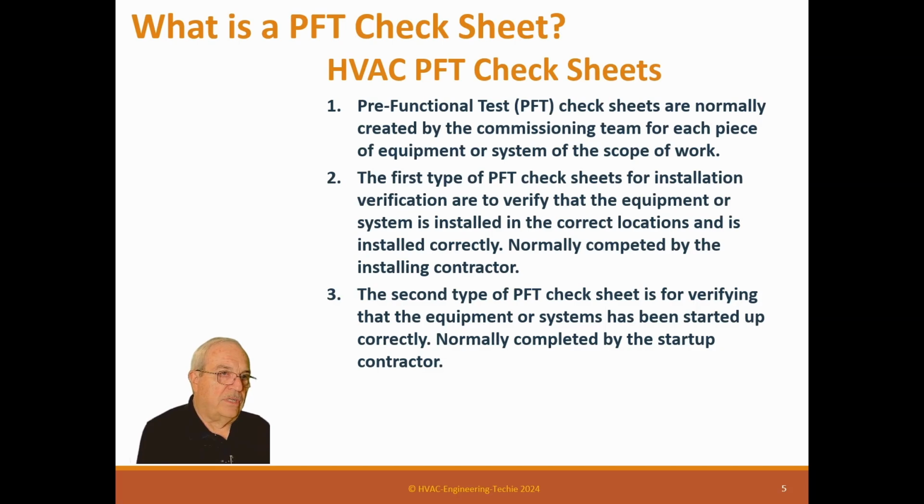So in other words, if it's a 480 volt motor on an air handler, we don't want the report saying, yeah, it's a 48 volt motor. No, we want to see 3 amp readings and 3 voltage readings for that 3-phase 480 volt motor. The reason is we need that data if we end up having to do any energy calculations on this motor, and we want to make sure it's correct.